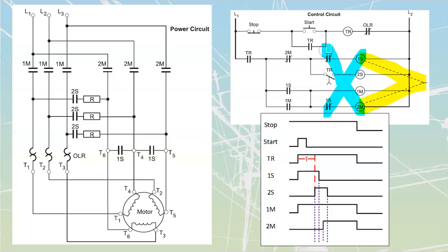This one's going to have a normally closed contact up there, so that we can't fire either one of these until the other one has completely settled back into its de-energized state. Other than that, we're pretty much the same through a lot of our control components. We're going to develop the timing diagram, and once we've developed it, we are going to transfer that to our actual power diagram that we're going to have off of here.